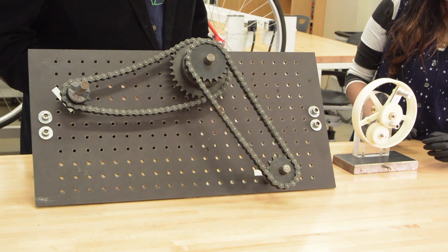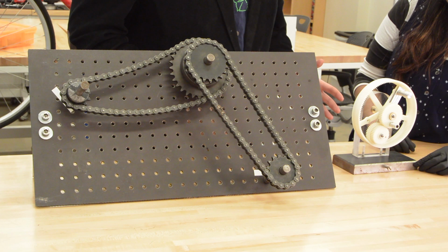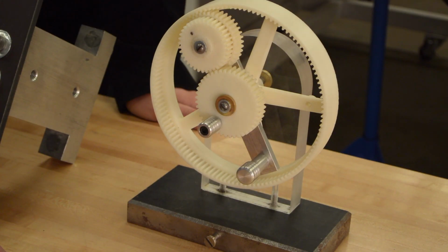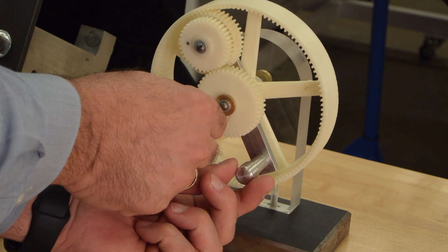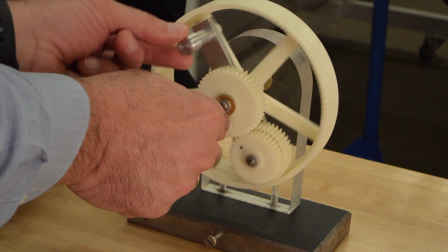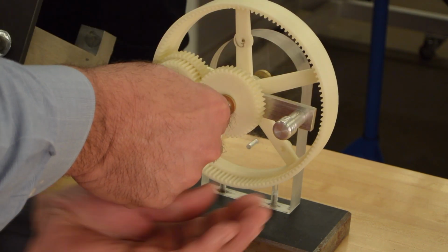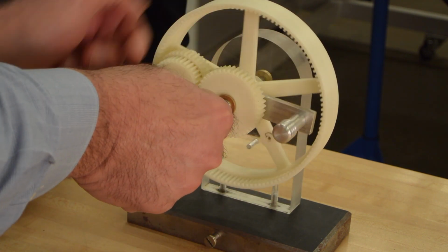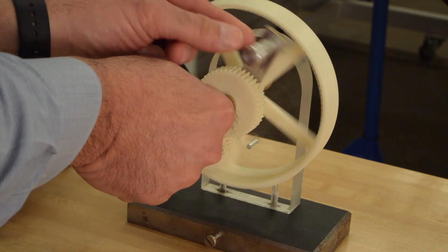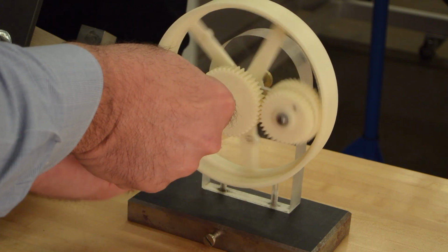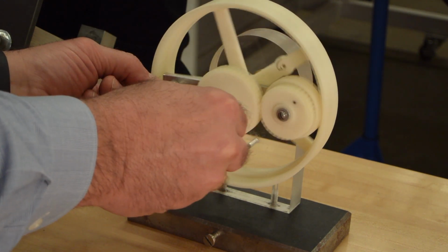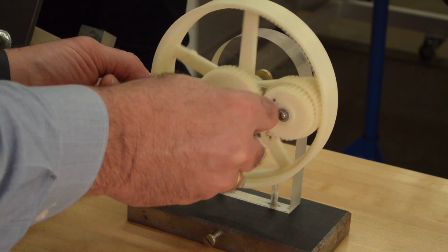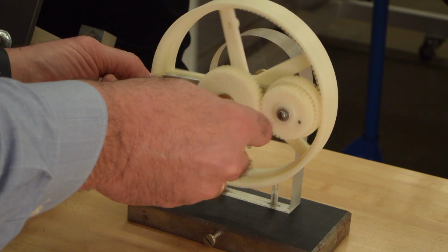On this planetary gear set, we can go a multitude of different speeds. This planetary gear system has 2 inputs, which together can be used to modulate the speed of the outer gear. Holding the sun gear fixed while moving the planetary gears causes the outer gear to rotate fast. Holding the planetary gear fixed while moving the sun gear will cause the system to rotate more slowly.